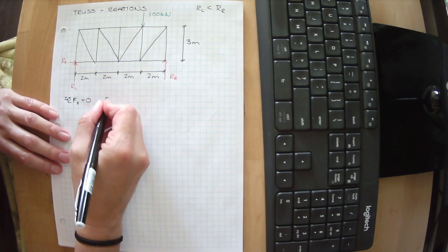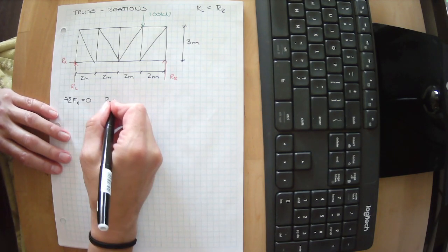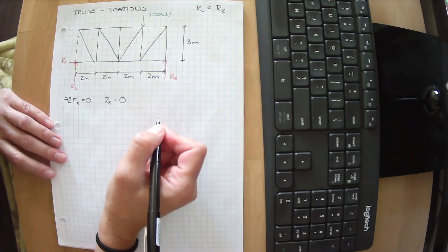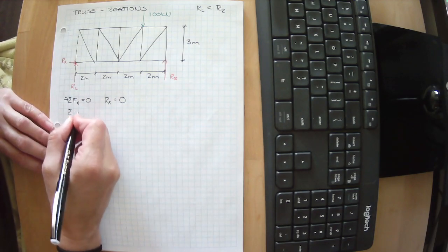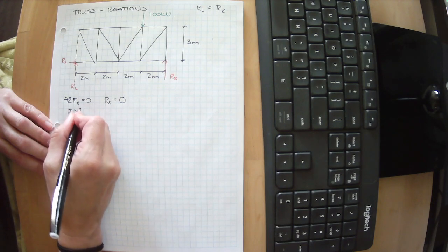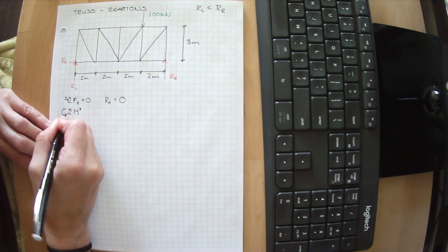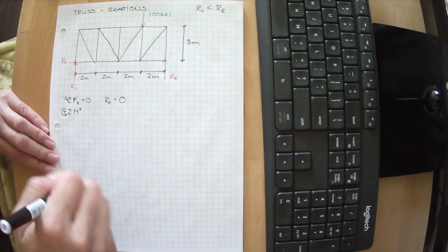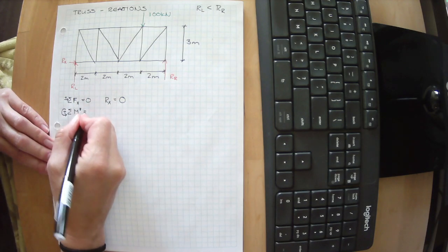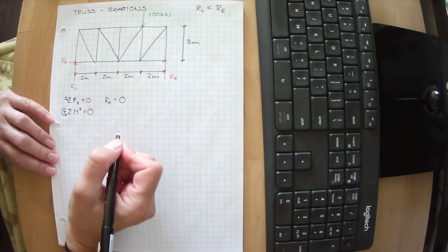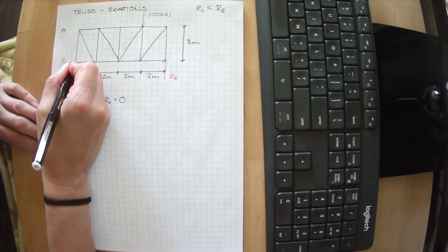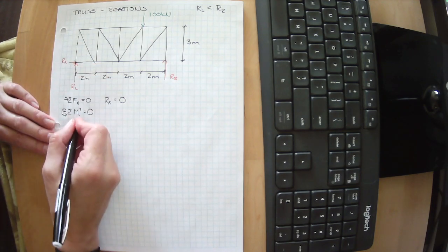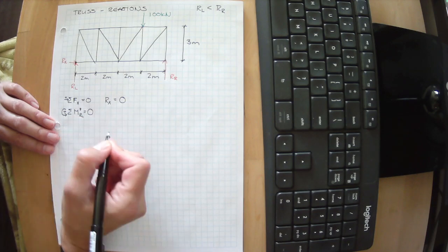Well, we have our Rx, and we don't have anything else. Our Rx does in fact equal 0. Let's sum our moments about the z-axis, where everything spinning in that direction is positive, and we want the sum of them to be 0. And let's pick the point that we're going to sum about. I've told you I'm pretty lazy, and I always do that point right there.